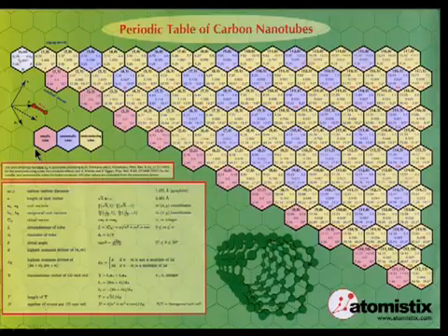So they behave like metals in terms of their electrical properties. And the sort of gray or tan-colored ones are semiconducting, meaning they have a finite band gap. So this one atom change, say going from a 6,6 to a 7,6 tube, can go from metallic to semiconducting.